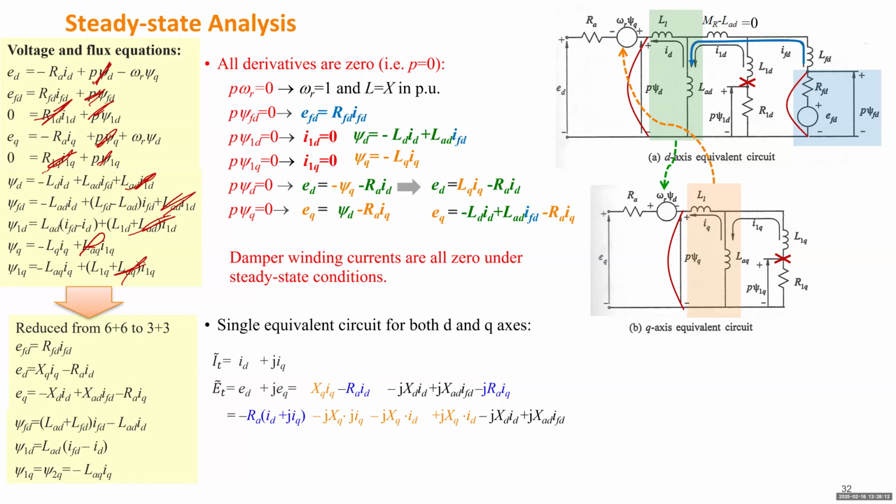So whenever we see i_q, we give it the imaginary unit, which means we also add another imaginary unit. Negative j multiplied by j will be 1. So this X_sq i_q will become negative j X_sq times j i_q. The next one creates another item which is the same as j X_sq, but multiplied by i_d. But this is a newly created item, so we have to add its opposite to cancel it. Those two just cancel each other. For anything else, we just move it here.